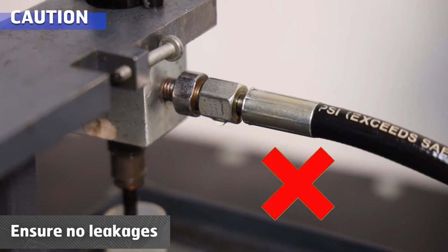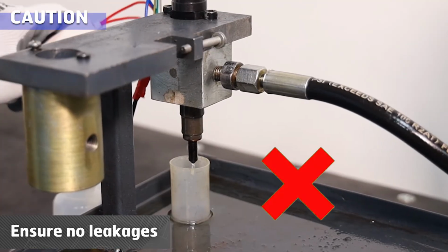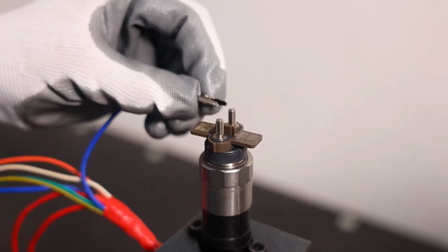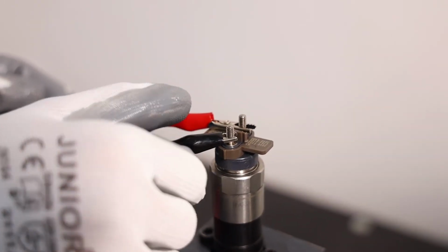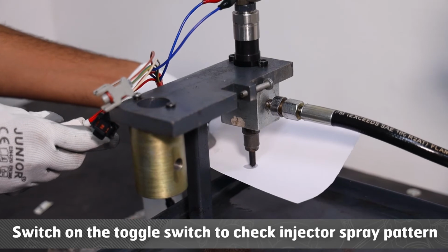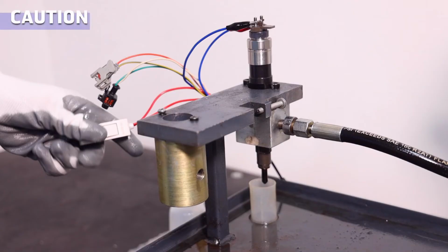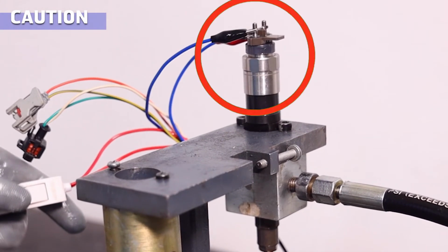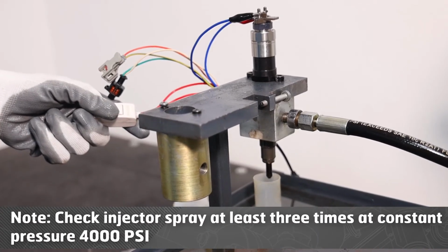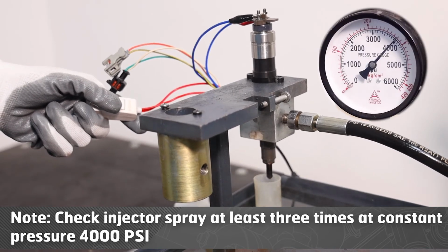Caution: after building pressure, check for leakages. Connect the electrical connector to the injector and switch on the toggle switch to check injector spray pattern. Caution: proper electrical connectors to be selected and ensure that shorting does not happen. Note: check injector spray at least 3 times at constant pressure 4000 psi.